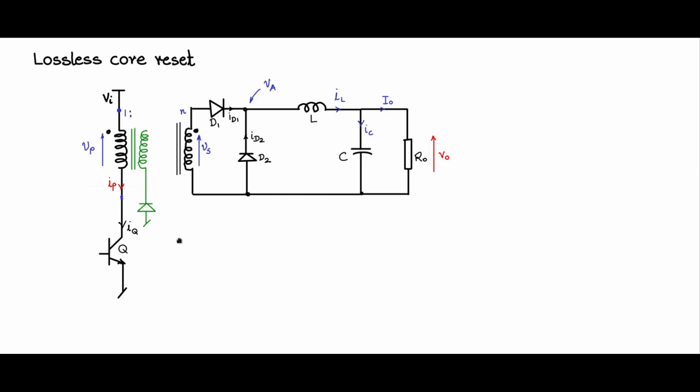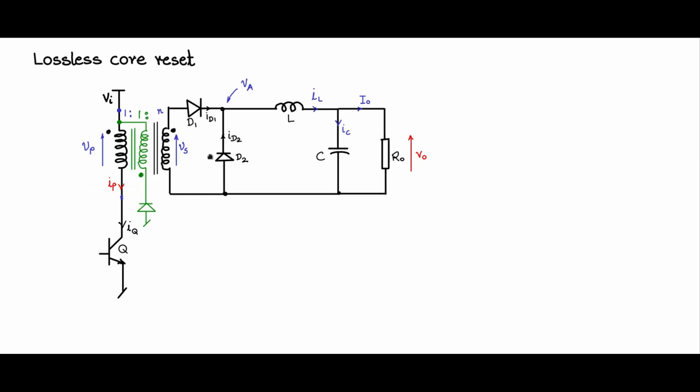And then you attach a diode like this, and the other end you connect it to Vi or VCC, and you place the dot polarity in this manner, opposite dot polarity. Okay. Then let me put this as 1:1 and let me push this back here.